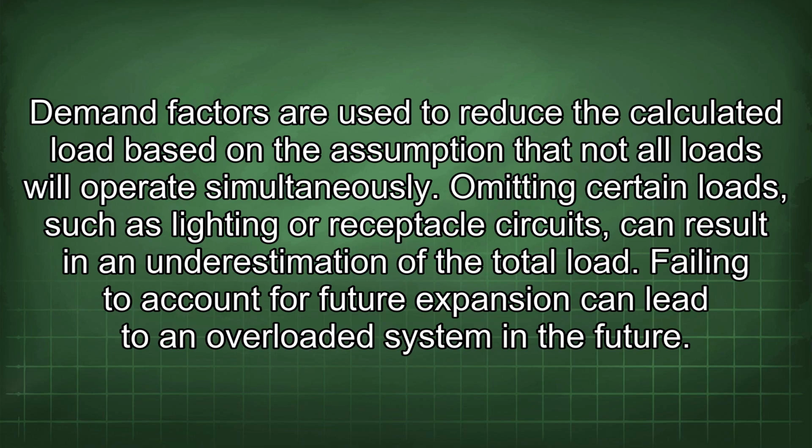Omitting certain loads, such as lighting or receptacle circuits, can result in an underestimation of the total load. Failing to account for future expansion can lead to an overloaded system in the future.